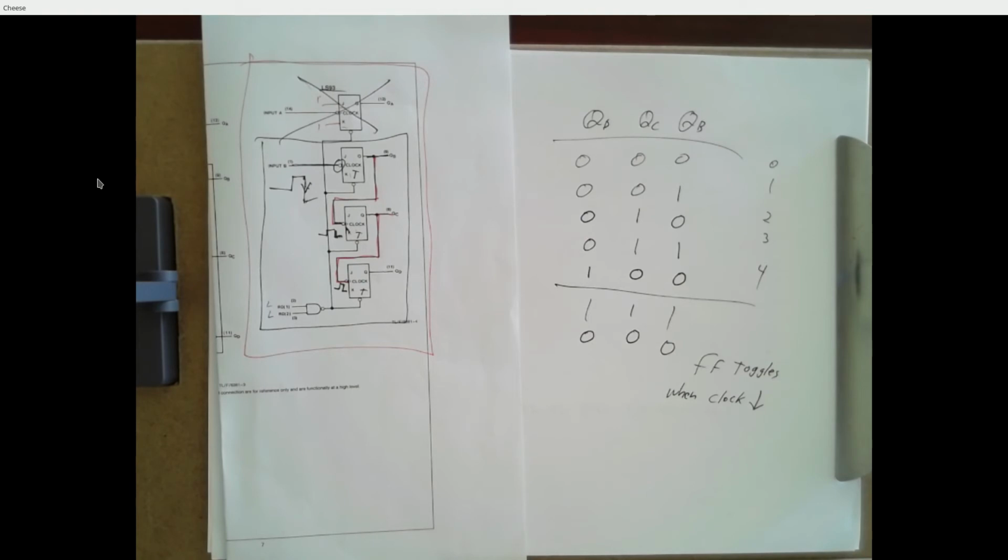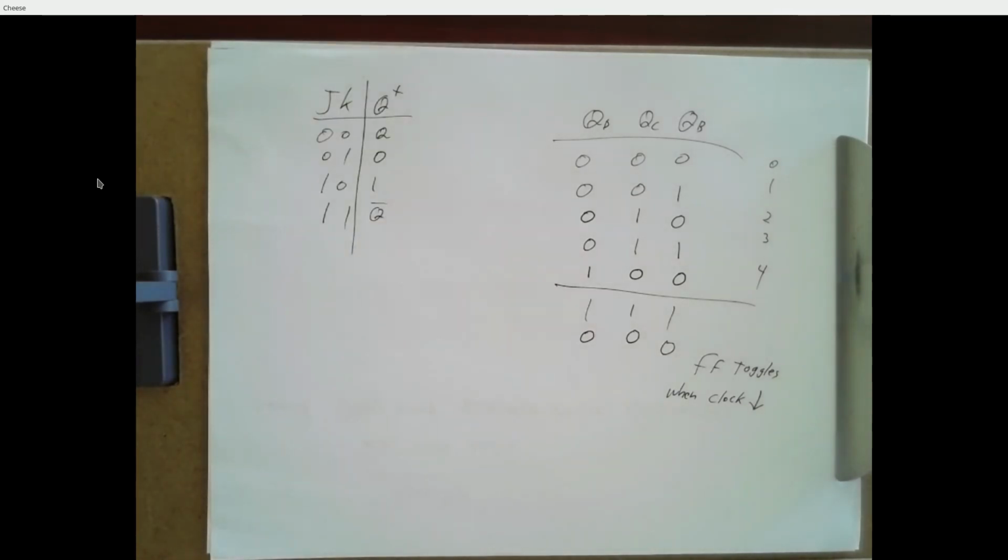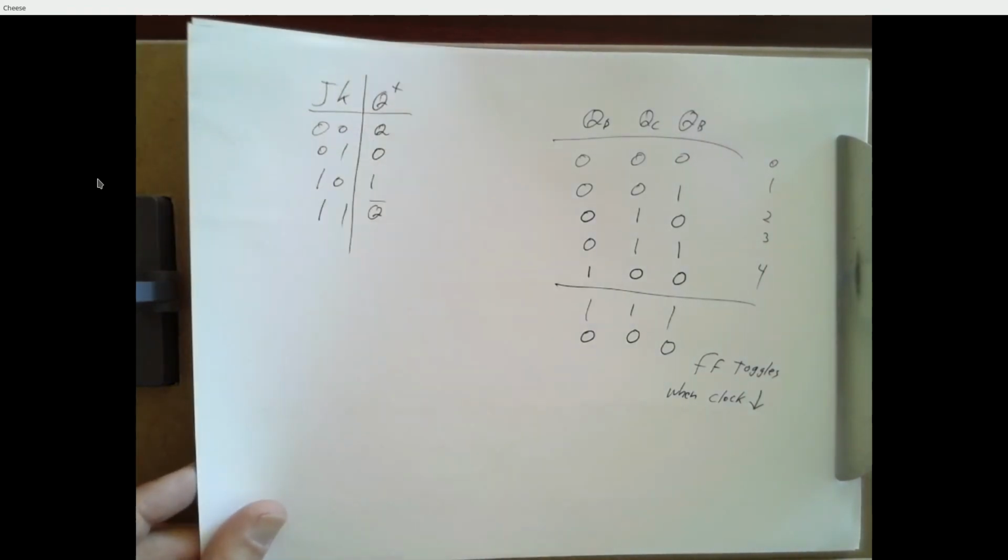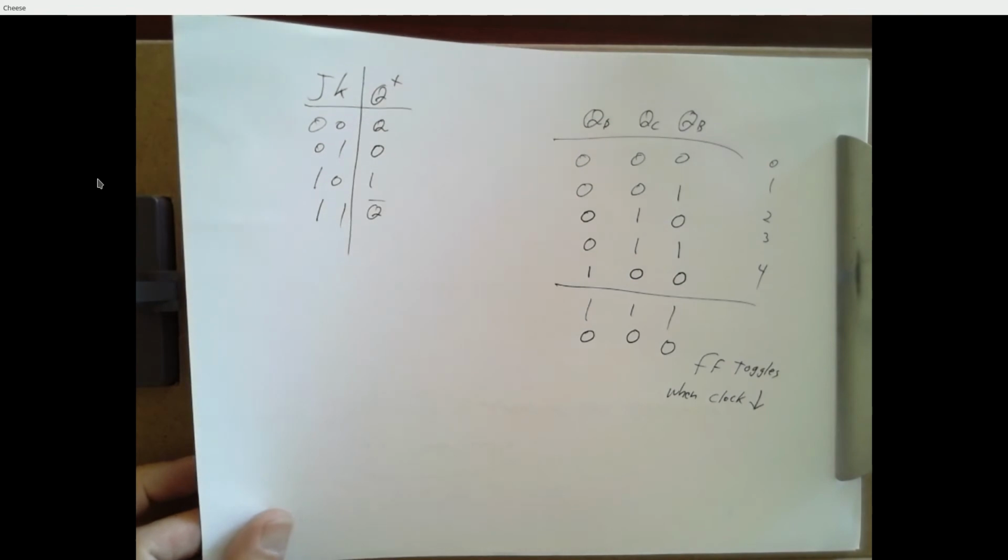Because we're talking speed of electron propagation, and this may not seem like a big distance, but if one clock signal has to go this far and the other one has to go this far, that can be a big difference in time. And if you're trying to run things at a gigahertz clock rate, that might be a critical difference. So clock distribution, whole discipline in itself. So don't mess with the clocks, but if you really need a counter with some T flip-flops, you can do that, right? It's not like a sacred law, but it's a guideline for making circuits that are easy to analyze and debug and make work properly. Okay, so that's what's going on inside the 7493.